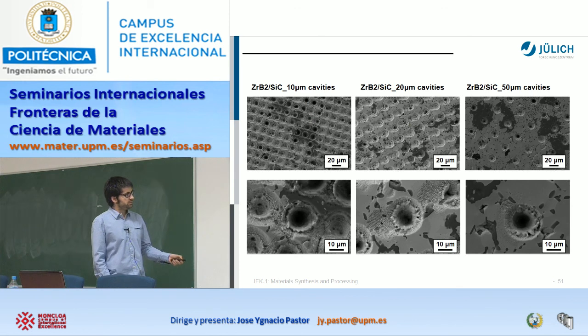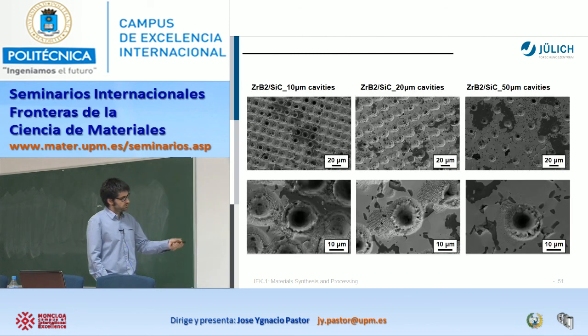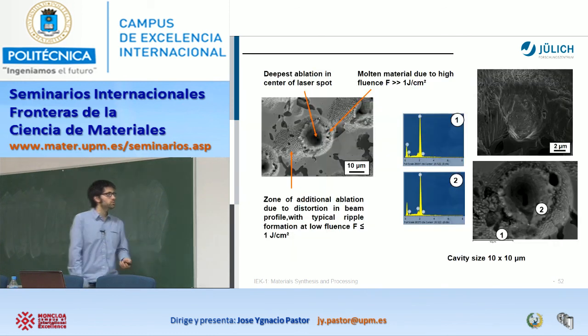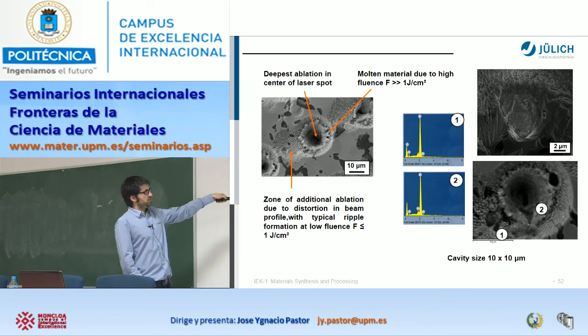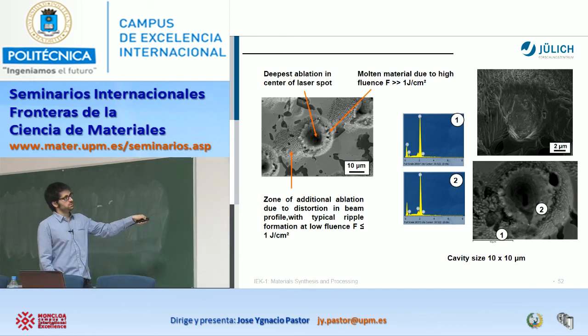And here that we see, I think I have, yeah, okay. Well, these are our cavities, and we can go into more detail and observe different things, but I think it's easier, yeah, exactly, to show here. But as you see, these cavities are formed, and all of them have a diameter close to 10 microns, okay? What we need to control here is the distance, because we didn't know the amount of gadolinium that we should incorporate. But if we analyze, because here obviously is where the laser impacts and makes the ablation, okay? That is here, the laser spot.